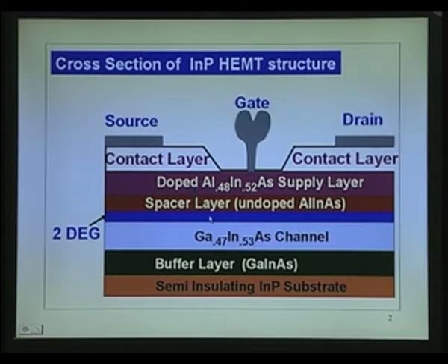Now, we saw there are various versions, because this type of structure gives a slight problem with the breakdown voltage. So, what they did was change this top layer to indium phosphide, which has a problem with Schottky barrier contact. Then another structure keeps the top layer like this, but instead of gallium indium arsenide puts indium phosphide. Now, the problem there is that lattice match is there, but the mobility of indium phosphide is low. So, you get high on resistance, all these problems are there.